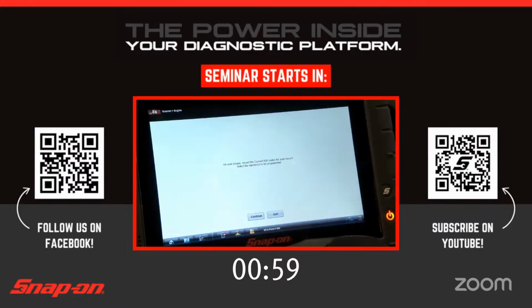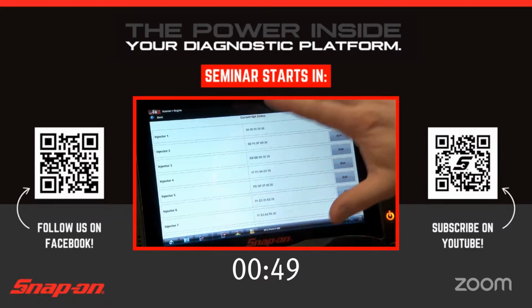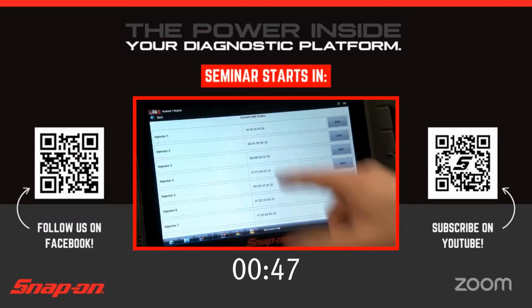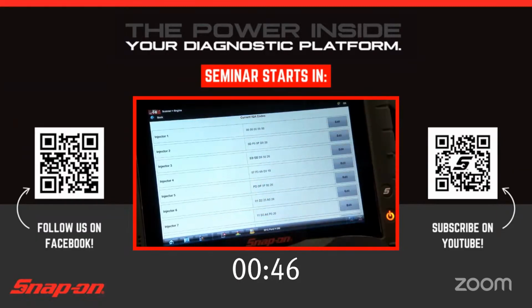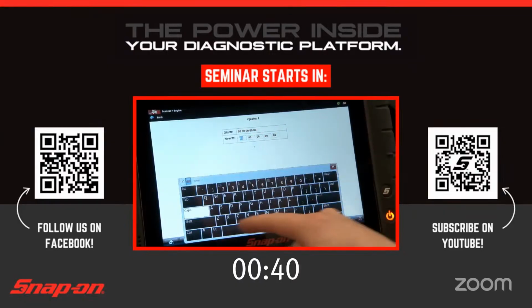On the next screen it says, record the current IQA codes for your record and select the injectors to be programmed. So hit continue. What displays is all of the codes that are already coded to the computer. We see there injector 1 is all 0, so we need to program that one in. So we'll just hit edit, and we'll program it in.